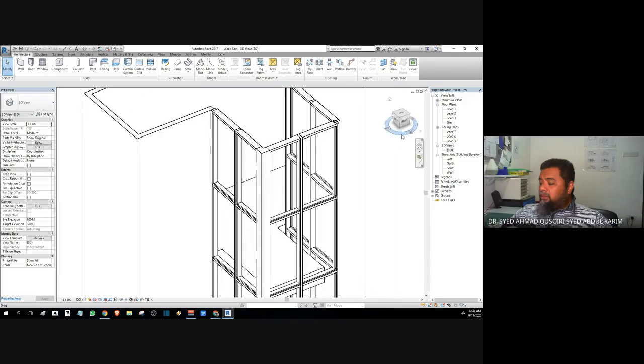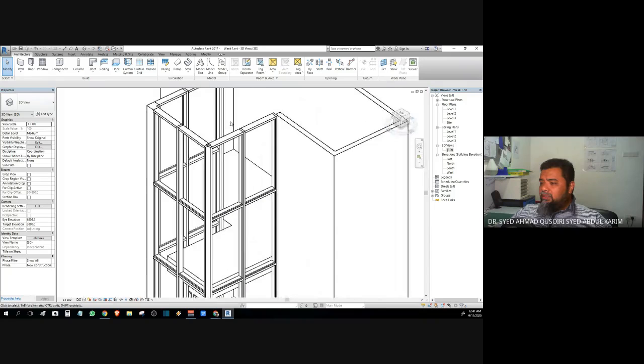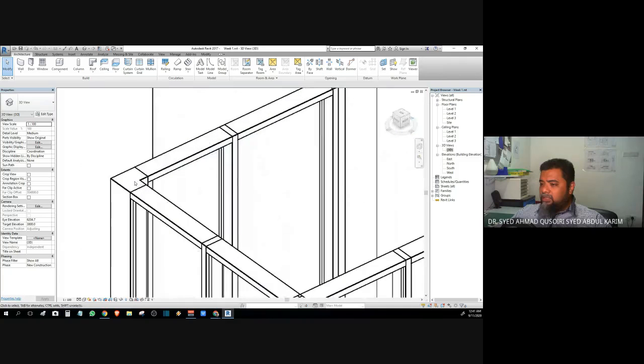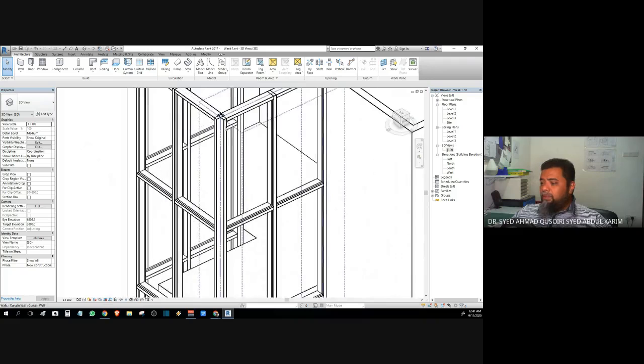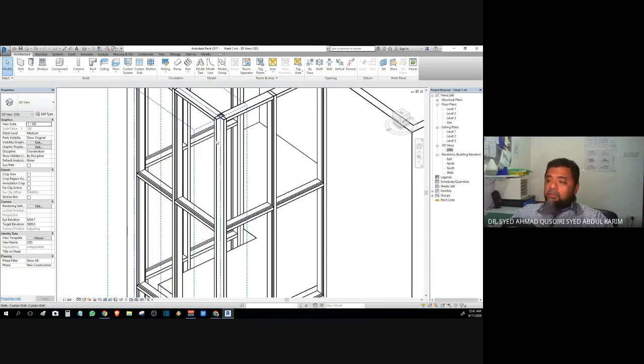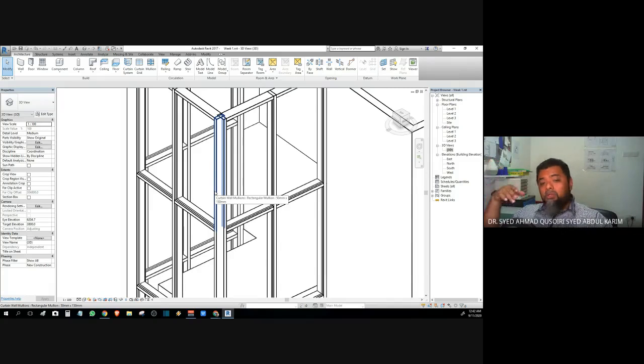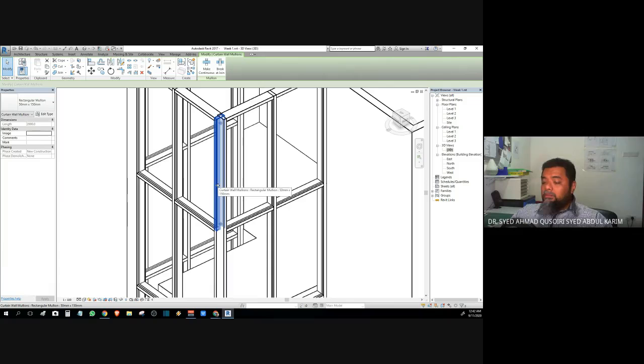So we have another corner to deal with here. You can see the difference here between the L shape and this overlapping rectangular mullion. So we have to change that. If you do not manage to click all the way down, it will only change the L-shaped mullion for the part you have selected, meaning that the bottom part will still be rectangular. We don't want that. Click here. Now I'm going to click side by side.